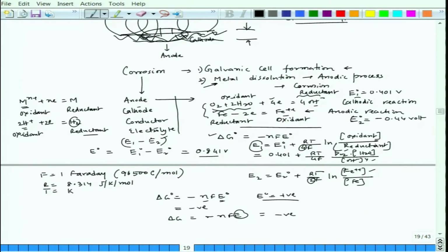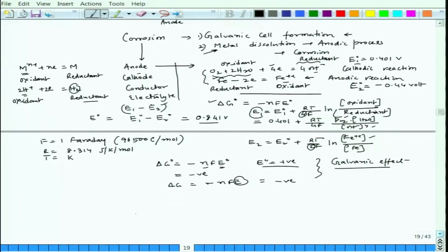So, now this particular effect is nothing but the galvanic effect. So, this is coming from galvanic effect, and this is a typical electrochemical galvanic effect. So, that means here the iron corrosion is actually a galvanic corrosion, but interestingly the form is uniform, because this galvanic corrosion is taking place over the entire iron surface. So, that means this is the iron surface. So, everywhere we are getting both these reactions, and there is no specific localized cathodic or anodic reactions.